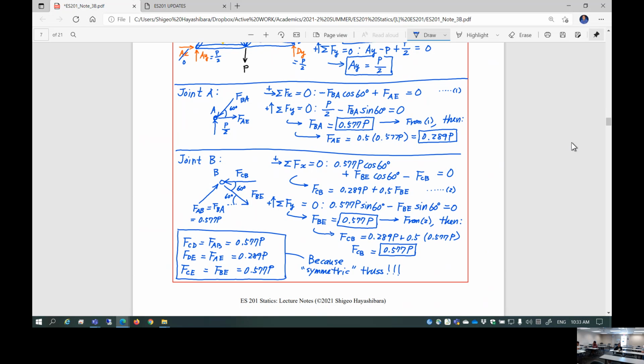Usually, that's going to give you 1 unknown force coming straight out of that equation. The other 2 are just a check, coming up with 2 reactions. So strategy is quite important. And also, you can observe and predict, hey, this must be tensile, this must be compressive. You can say that before you even apply the direction of the force at each joint. So quite a few important things.